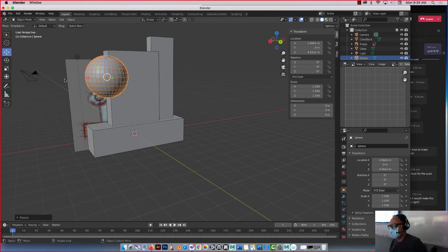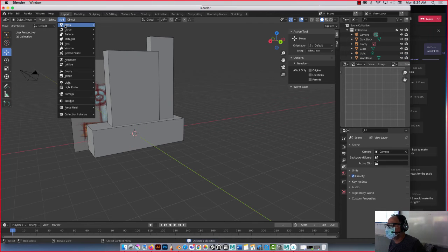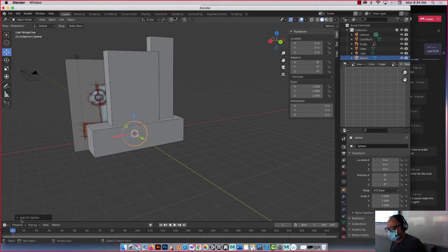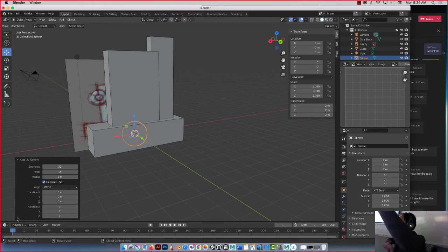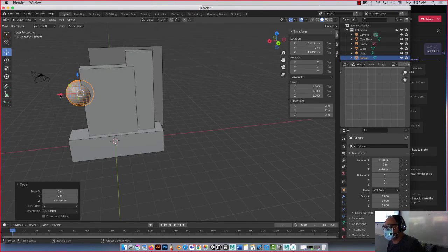Oh, yeah. Now, the minute I resize this, I lose control of all these faces. So watch again. I'm going to delete this, okay? Press Delete. So you go Add, Mesh, UV Sphere. Now watch. Because this was hidden before, this app has a lot of hidden little menus, okay? So look, 32 sides. Nah, man, I don't need 32 sides. Let's say 24. I don't know, 24. Okay? Watch this. I'm going to bring it up. As soon as I move it, I lose control of this. Okay, at this point, let's leave it like that.